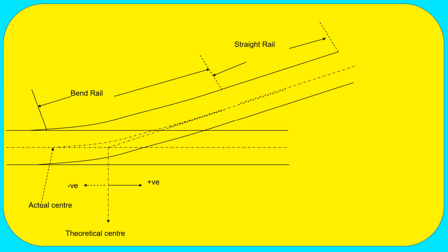First anchor, then it will be raised, then it will come to the crossover point. For cross type, the anchor must be next to the crossover, just one span. Knuckle type is also like that, but we have extended one span for overlap type.